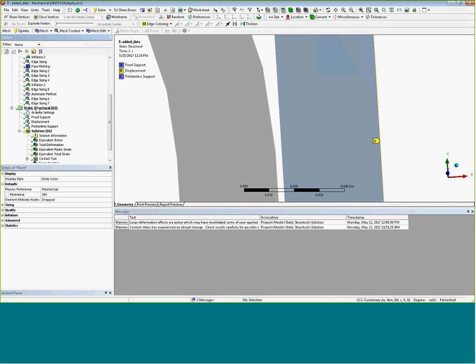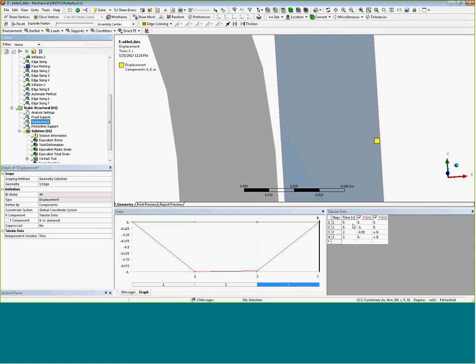I also used a displacement control solution. I ran this in 3 load steps, where in the second load step, I just did a very, very small amount of unloading. That typically gives me the best convergence because ANSYS has to convert from being on the loading curve to the unloading curve. And computationally, doing that in a very slow process is much more efficient to get that problem to solve.